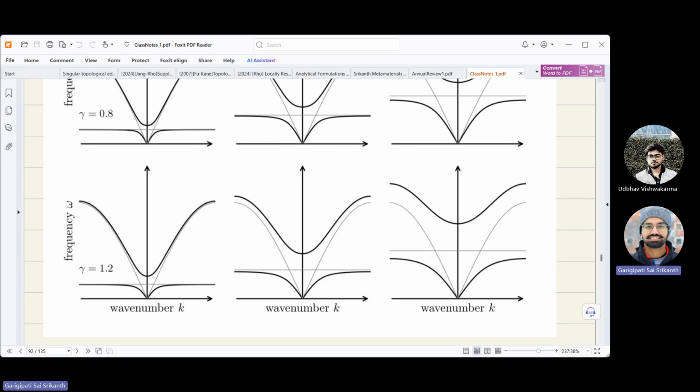And if you think of your unit cell, your mass-in-mass system, that inner mass is connected rigidly to the outer mass. That means it's not an independent degree of freedom. It's a monomer. You now have a monomer where your total mass, instead of, let's say, small m, is now small m plus capital M. That is your total mass, and you have only one band.